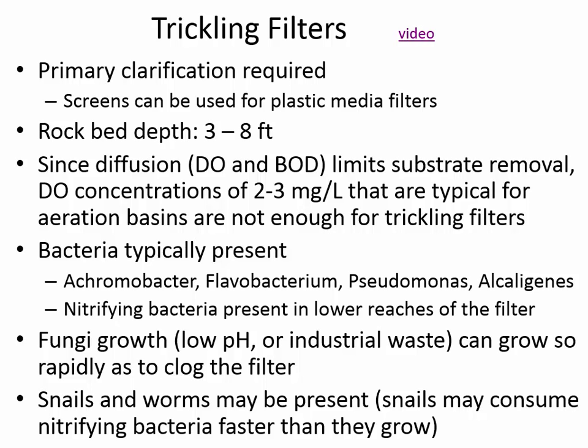But in the case of trickling filter, especially during periods of low flow rate, in the middle of the night, if you think about how slow that arm would be moving if there was a very low flow rate and they didn't recirculate to try and keep it moving, it's possible that either the bacteria could dry out and be killed for that reason, or that during other periods the bacteria could grow so quickly and the slime layer could actually clog.